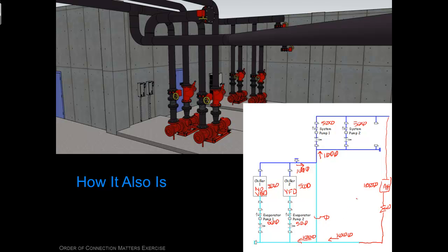In the field, there's enough noise in systems that there's always a little bit of variation going on back and forth. This will be 1,010 and this will be 990, and then it'll flip, because little things going on affect things. But virtually no flow in this bypass at full load. That's how the plant's intended to work. Now let's unload the plant 25%. So I'll change colors.